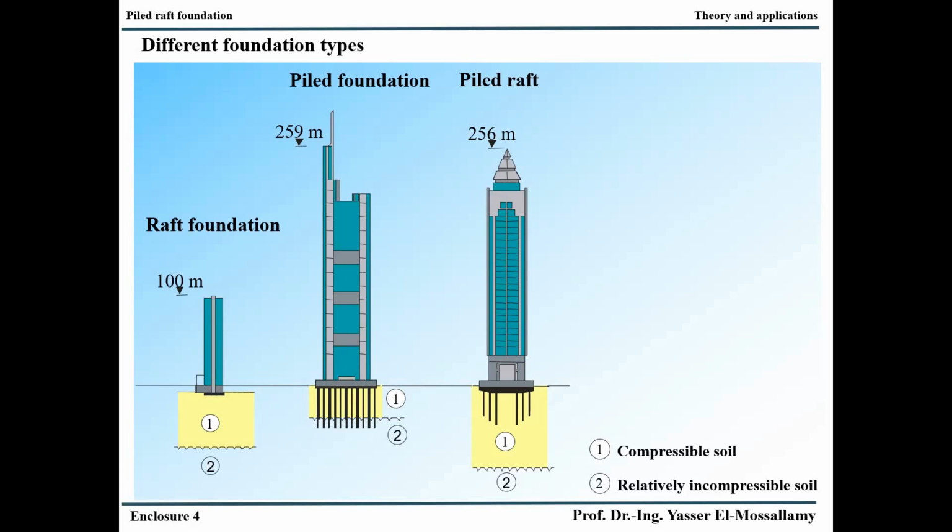Below it, we have limestone. Therefore, if we apply in such a case conventional deep foundation, the piles should be more than 100 meters long, and this, of course, is not very suitable and not economic.